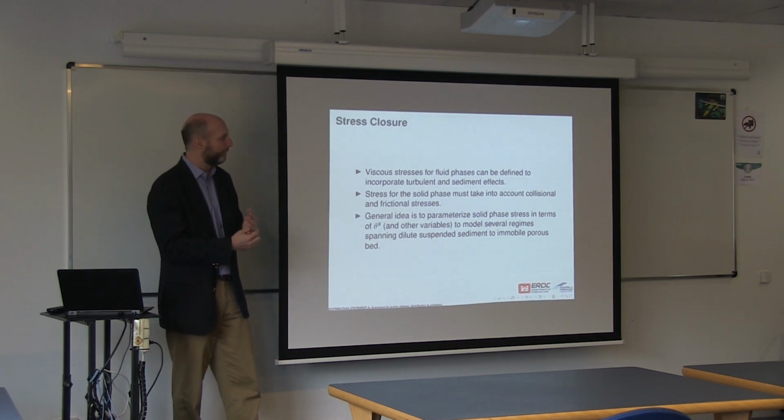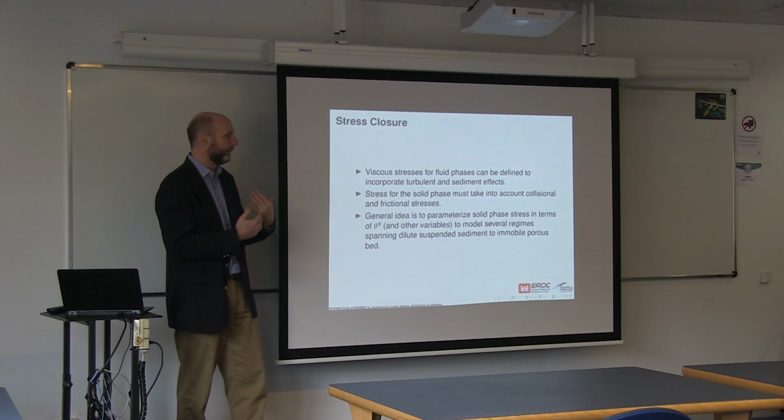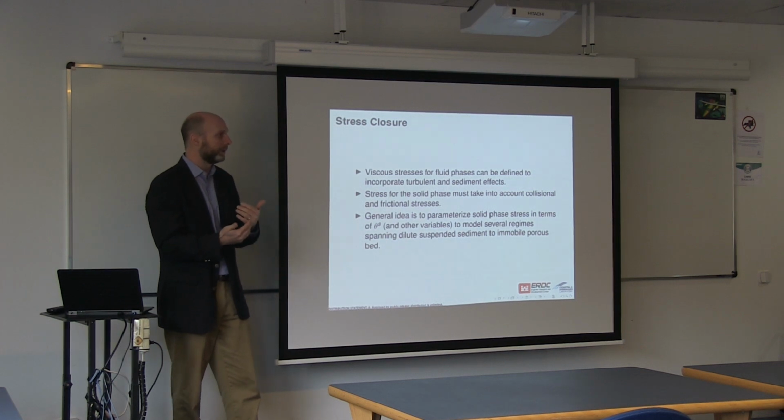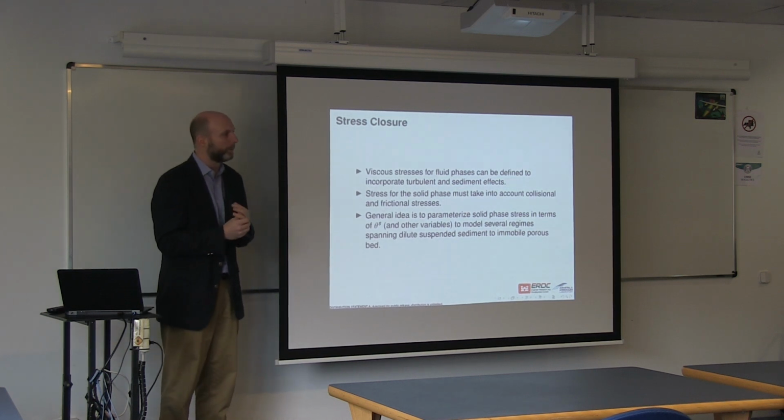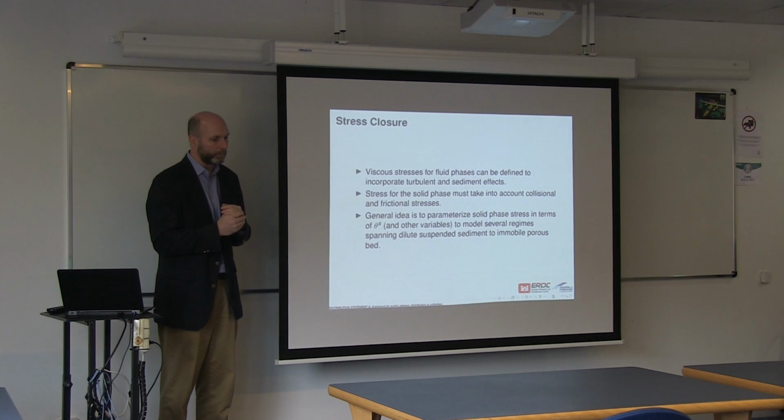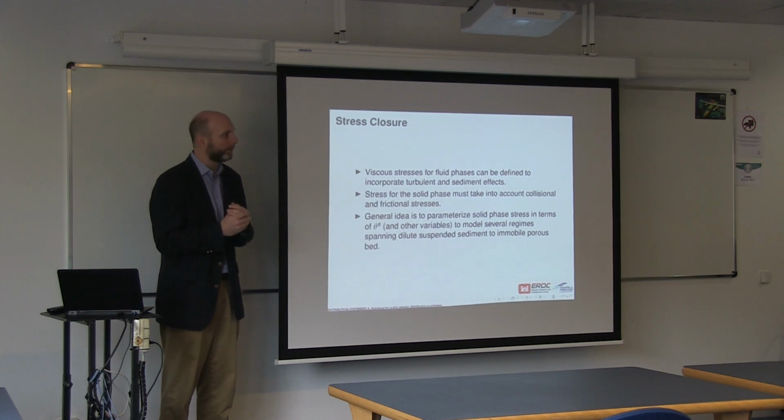My gut feeling is that the immersed boundary method, even though the one that we're using is clearly lower order, may actually be helping stabilize the partitioned FSI simulation, because it's less sensitive to the motion of the boundary. It smears it out a little bit, and so you get more stable computations of drag and lift. So that's why you're using it. Yeah, but we'd like to get the SBM working and look at some of the other approaches, obviously. It would give us the provable higher order accuracy.